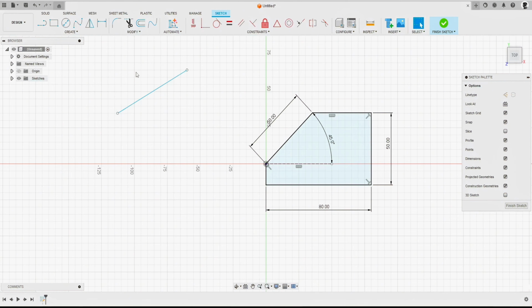And then another option as well, if we left click and drag up like this, notice that it's a different colored square. So this one here is an orange with a purple border. One here is yellow with a dash border. All this means is that any entity that comes into contact with this area will be selected. I let go now, you see we've selected that line. But if I do the same thing and drag across like this and let go, I've not selected it. That's a really useful tool when we're working with Fusion. Just drag across like this. There we go, I've selected it, hit delete on the keyboard. Now we're left just with our sketch there.